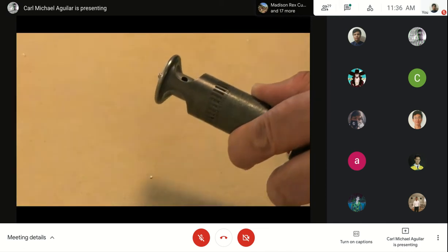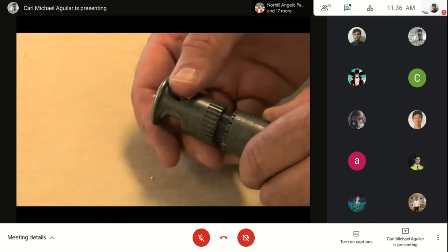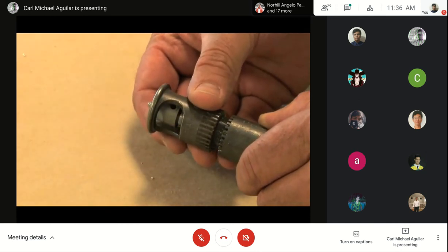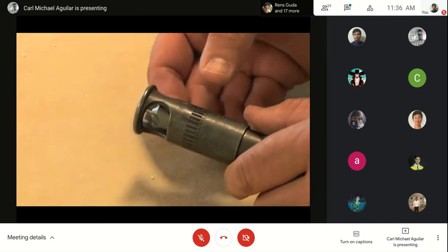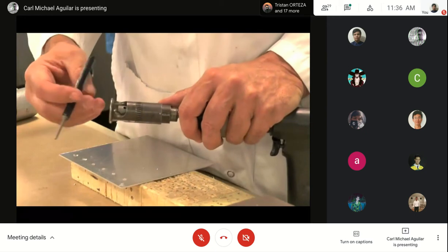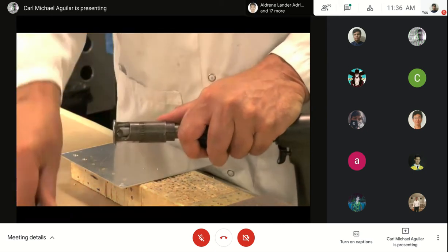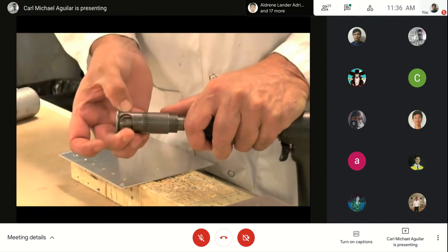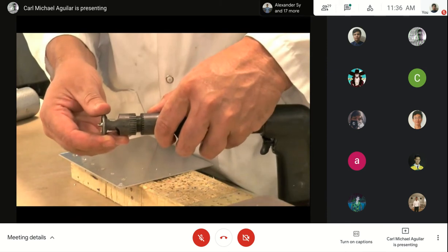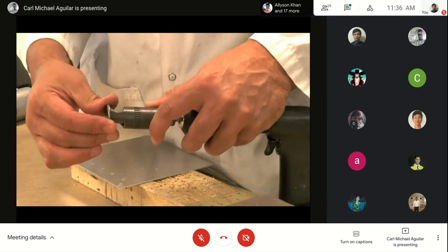The microdial body is extendable, which determines the depth of the countersink. Each castellation on the housing equals a value of 1/1000th of an inch depth. To change cutters, break torque using a pin punch and rotate to remove. If the body length is shortened, the cutter penetrates deeper. If the microdial body is lengthened, the cutter depth becomes more shallow.